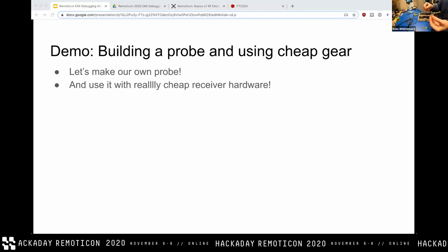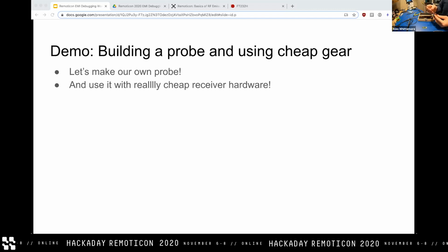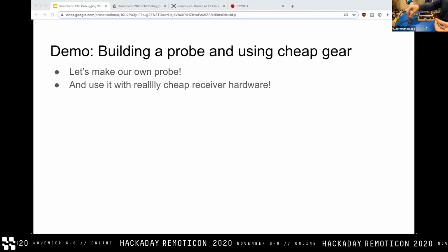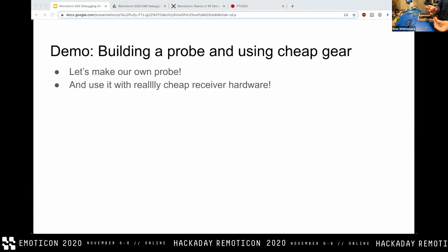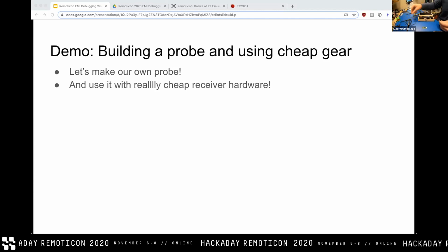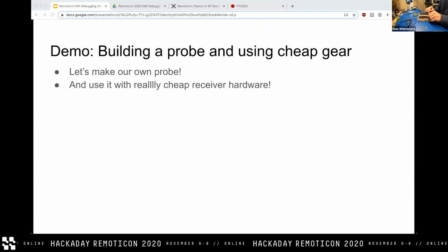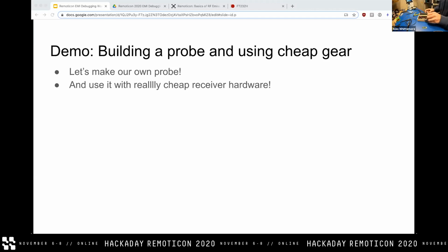So I bought a couple of SMB connectors after the fact and added them. I guess actually I bought these SMB connectors so that I could just use this cable to go back and forth between these two probe sets while I was working. But I encourage, if you're making probes, probably use SMB connectors, you know, with a handle just to make things easy on yourself. But you don't have to overthink it; they'll still work.